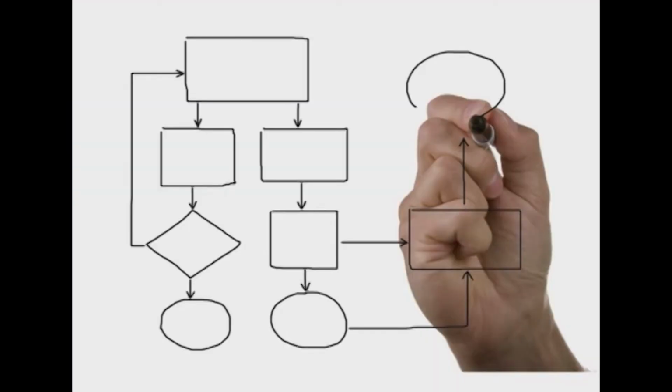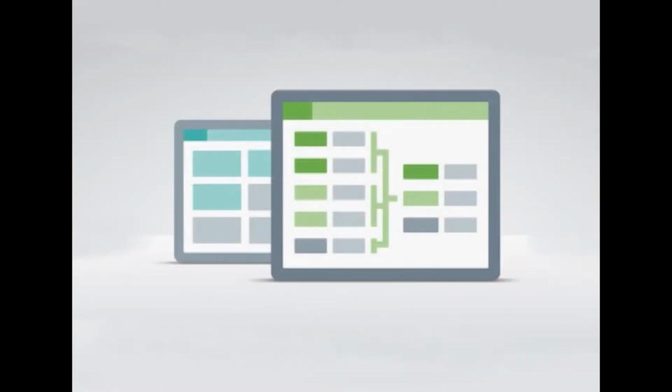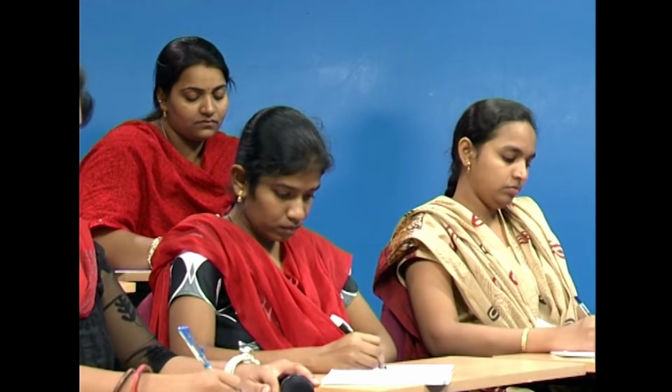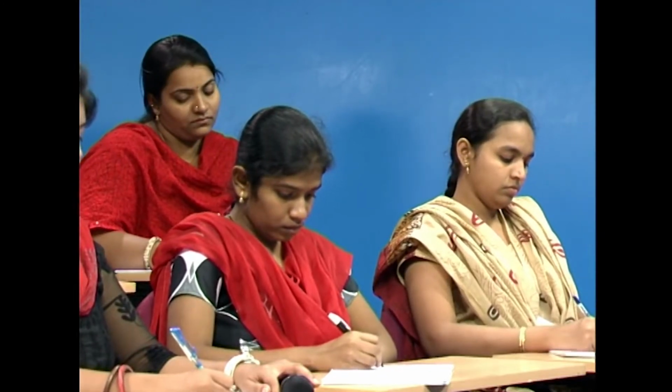Control charts. The control chart is a graph used to study how a process changes over time. Data are plotted in time order. A control chart always has a central line for the average, an upper line for the upper control limit and a lower line for the lower control limit. These lines are determined from historical data. By comparing current data to these lines, you can draw conclusions about whether the process variation is constant, in control, or is unpredictable, that is out of control, affected by special causes of variation.